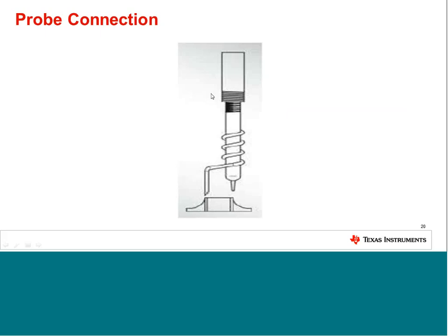So what you see on this picture here is a simple solution to fix this problem with a standard probe. So you just use a copper wire, wind it around the tip of the probe to connect the ground, and use the tip directly at the input capacitor.